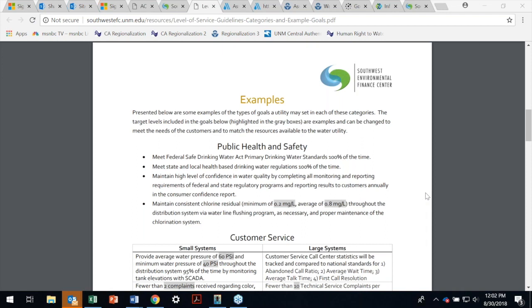Other than that, why would you be maintaining it, unless it's like an air valve or a scour valve? Different story. But the actual pipe itself, if it's a critical pipe, a big pipe that's coming into town from the bore field or wells, even in the middle third of its life, you might go, well, there's probably not too much to do unless something's happening. Once you get this highly critical asset and it's in the last third of its life, I should know what I'm doing, and maybe I should have a preventative maintenance schedule. So it's useful to consider what phase of life the asset's in, and if it's critical and getting into the last third of its life, see what you need to do to manage that risk.